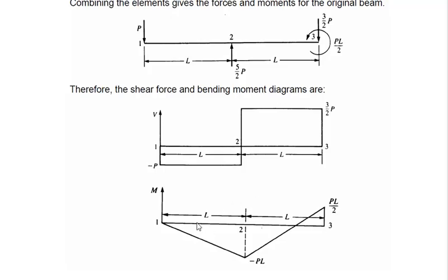And then we can draw the bending moment diagram. At free end, moment is 0, and then we have this negative area, minus P into L. So we come to minus P into L, and then this positive area, which is 3 by 2P into L. And when we add it to minus PL, we reach PL divided by 2. And here we have PL divided by 2 in the clockwise direction. So that brings the bending moment diagram to 0. So that completes this problem, the first problem.